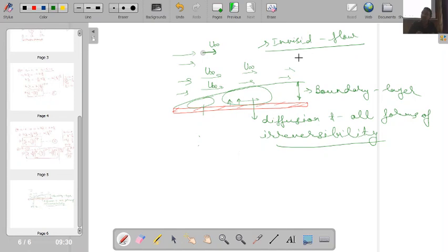is not something practical, for the majority of compressible flow situations, irreversibilities are associated only within the boundary layer region, which is very thin and just adjacent to the aerodynamic body or the surface we are considering. Away from that, we have the large portion of the fluid element, because the thickness of the boundary layer is very, very small. There we don't have any viscosity dominant situation. So it means we don't have the irreversibilities,